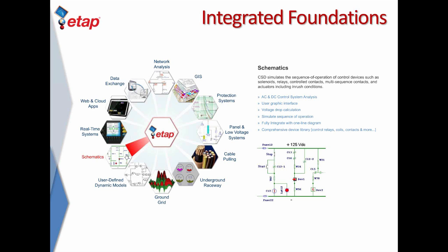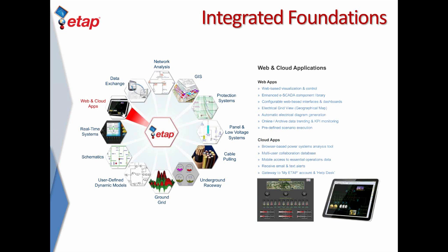As I mentioned, ETAP network model that you use for design and planning can be migrated over to a real-time system where the model is connected with the real-time data, and we run various advanced applications on that model, such as predictive simulation, intelligent or fast load shedding, various energy management functions, as well as microgrid controllers. The same information can be visualized using web applications such as your web browser. In fact, you can also even run certain scenarios directly from your web browser without actually having the ETAP application open, so it gives you a lot of flexibility.